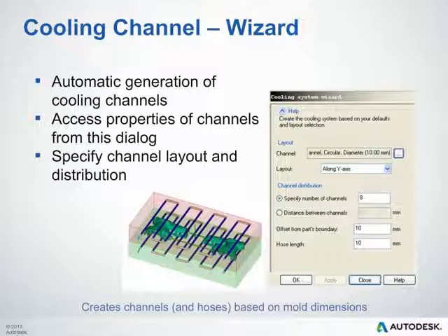You can also specify a channel layout and distribution in here. So you can see the number of channels we're specifying. You could specify the distance between channels or just offset them from the part's boundary. There are several options here.